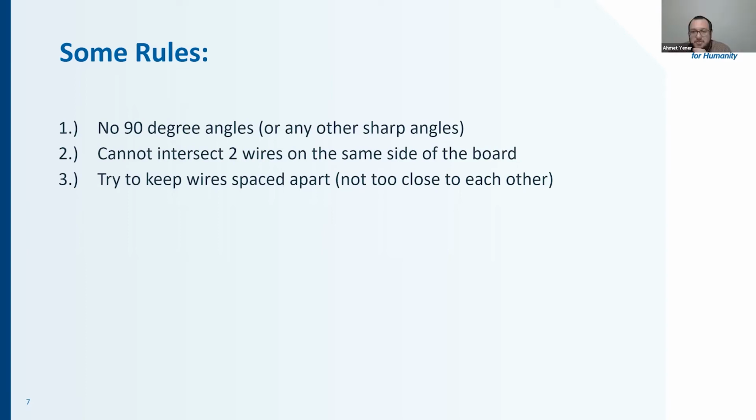Or you might burn your board down if you put 90 degrees. Yeah, I would hope that there aren't any boards that would just catch fire at 90-degree angles. But think of a flow of electrons as like a flow of water. If you have electrons going one way really, really fast, typically you want to avoid sharp angles. You want to do something rounded or do a couple of 45-degree angles. It's best to do that because you're going to get a better flow of electrons.